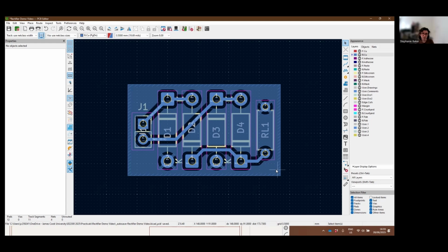The other thing is that for more advanced circuits, you might also have multiple planes. So for example, you might not just have a ground plane, you might also have a power plane, or you might have separate ground planes for your signal ground and your power ground. Again, all of those concepts relate to more advanced circuits that you'll cover in future subjects, but it's just a skill set that's worth practicing and having. So I really recommend that you do your grounding with a ground plane and think about where that ground plane is to make your life easier.